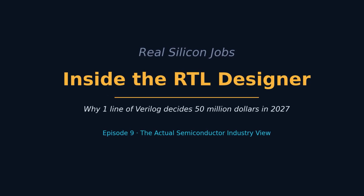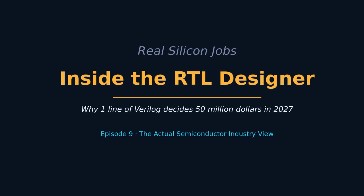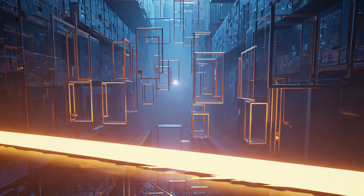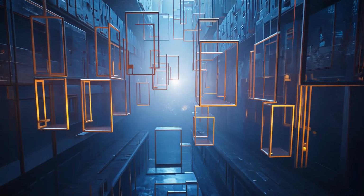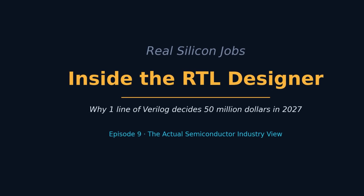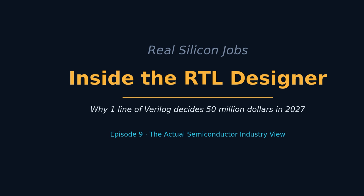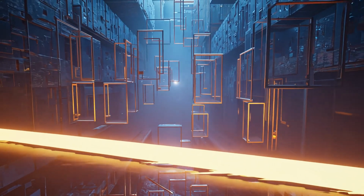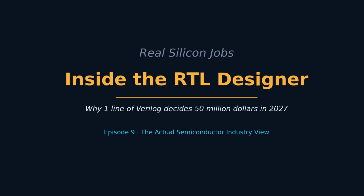Here is a single line of Verilog code worth $50 million, always at posedge clock. Inside it, a register that should reset to 0 on every cycle. The engineer who wrote it forgot the reset. 18 months later, that one missing line returns from the silicon as a chip that hangs intermittently in customer data centers. $50 million of warranty claims, recall, and lost revenue from one line.